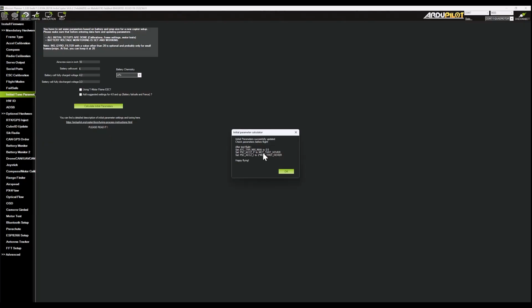It's related to motor thrust hardware, which thrust you can potentially use in order to start hovering. But once again, I'm not sure if it's something that can be learned very well. Yeah, so you can potentially not touch anything. After that, since we are going to go deeper and do tuning of PID of all parameters later using the autotune procedure, at least this parameter you can set to 0.5, or you can experiment even with these parameters.